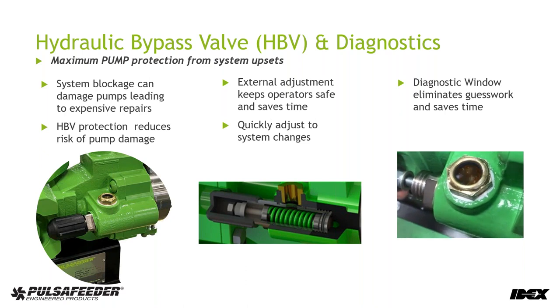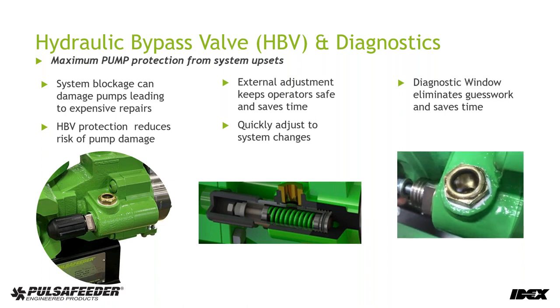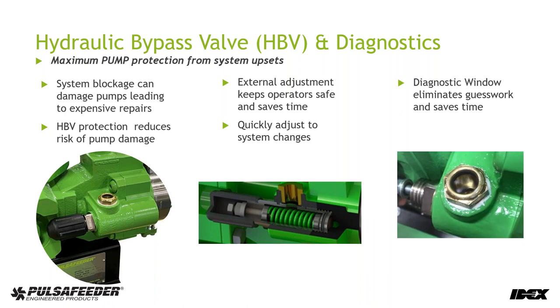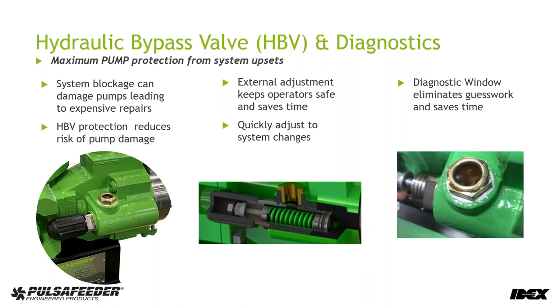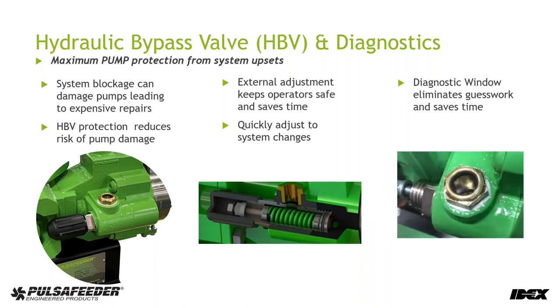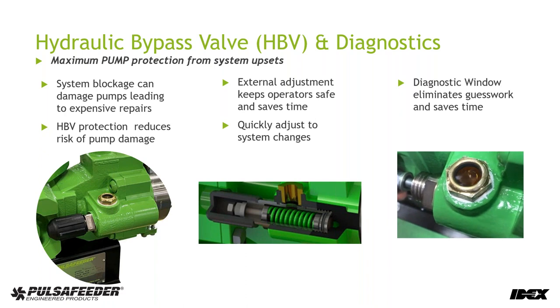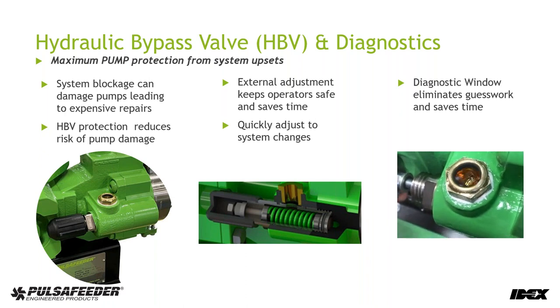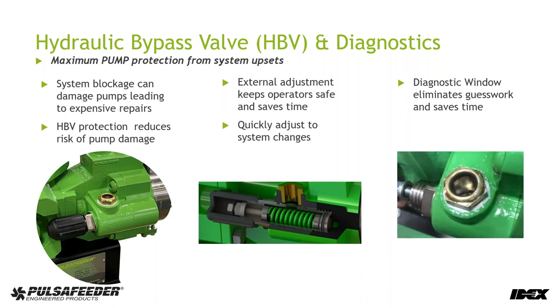I just really want to emphasize, this protects the pump, and every system should have an external pressure relief valve in its line, so you protect your system. Need to put that out there. But the hydraulic bypass valve protects your pump, and more importantly, your personnel with safety, and gives them further insight into the pump condition. So we don't want any more operators sticking their hands down inside of oily reciprocating pumps to try and adjust them and set them up. That's eliminated with the PulsaPro hydraulic bypass valve and its diagnostic window.